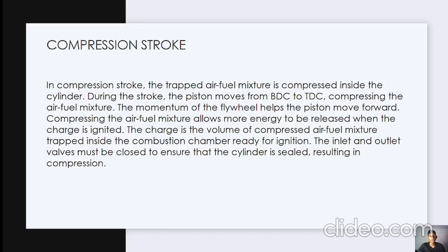In the compression stroke, the trapped air-fuel mixture is compressed inside the cylinder. The piston moves from bottom dead center to top dead center, compressing the air-fuel mixture. The moment of the flywheel helps the piston move forward. Compressing the air-fuel mixture allows more energy to be released when the charge is ignited. The charge is the volume of compressed air-fuel mixture trapped inside the combustion chamber, ready for ignition.